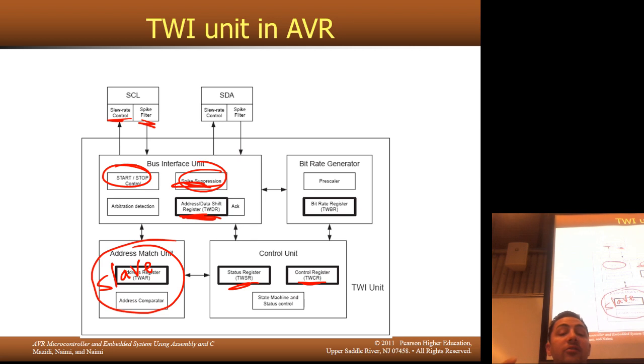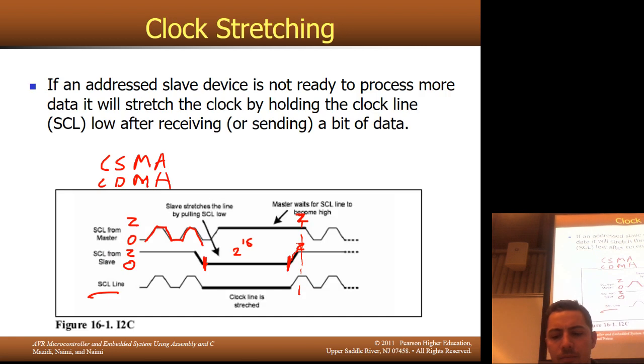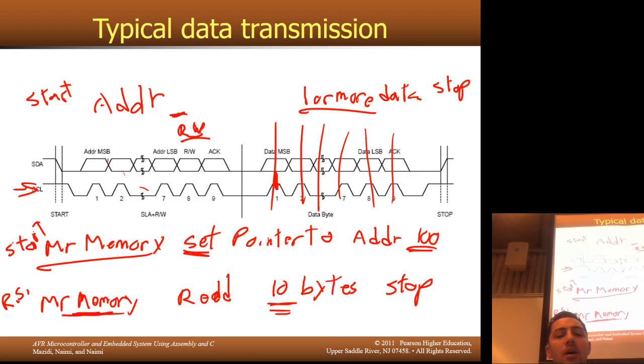Remember when I was talking about Mr. Memory? Did I leave that ink on the slide? Mr. Memory. This whole thing is one command. Read into memory from this. It does both things. It deals with the repeated start, does it all, and gives it right back to you. I²C is a highly defined protocol across any kind of device. It doesn't have to be just a memory device. It could be a real-time clock, which may come in handy in about half an hour.